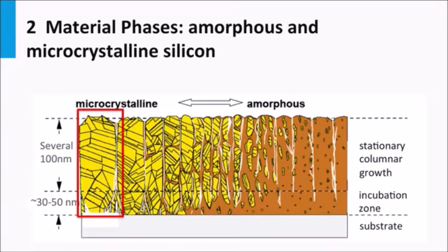Going from right to left, the amorphous phase is changing into a mixed phase with a few small crystalline grains, to a phase which is dominated by large crystalline grains and a small fraction of amorphous tissue. The best nanocrystalline silicon bulk materials used in solar cells have a network close to the so-called amorphous to nanocrystalline silicon transition, and the crystalline volume fraction is in the order of 60%.